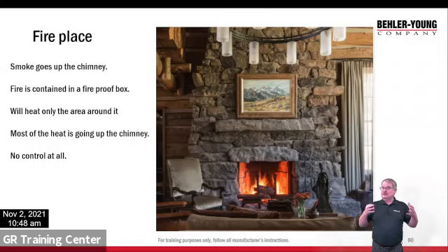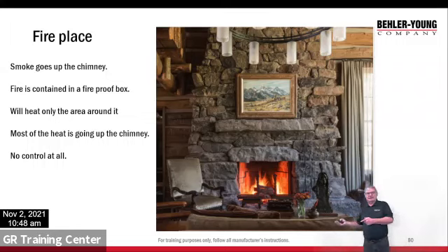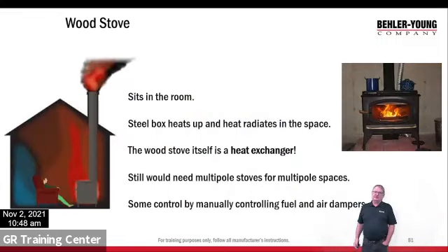But it's only heating out in front of it. So if I'm sitting in that couch right there, I feel the heat in the immediate vicinity. If I walk in the next room, it's cold. Because we learned a word today, combustion air. Guess what? That fireplace uses combustion air. And where's it coming from? It's coming from this house. So we're actually taking air out of the house, and we're heating up that chimney to feed that fire. All right, no control. We're only heating the space we're in.